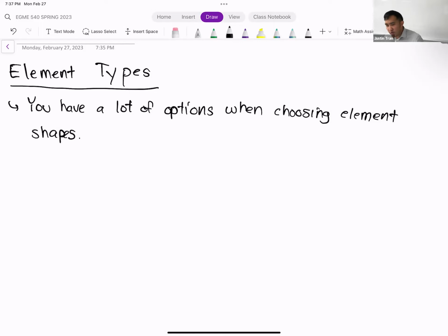So we know that triangles fit better in some situations when you want to mesh no matter what, okay? Whereas the rectangular elements or the quad or the hexahedrals, those work better when you have a square geometry with filled space, okay? The differences go a little bit deeper than that. And so I want to talk a bit more about that today. And so, hopefully after today and Wednesday's lecture, you'll have a better idea of exactly why people consider the rectangular elements to be a lot better. Okay.